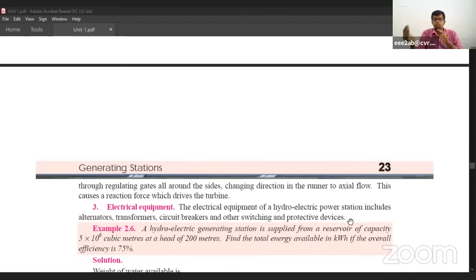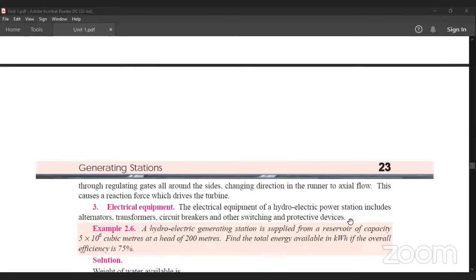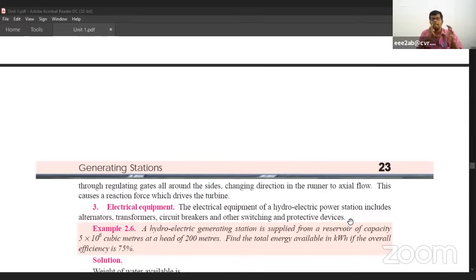We will be taking one phase to some two rooms, one phase to some two ACs, one phase to some other rooms, like that. So if your AC is on, you can go to the nearby meters and find which phases are taking more supply. Also you can easily find out nowadays due to the modern electronic meters.